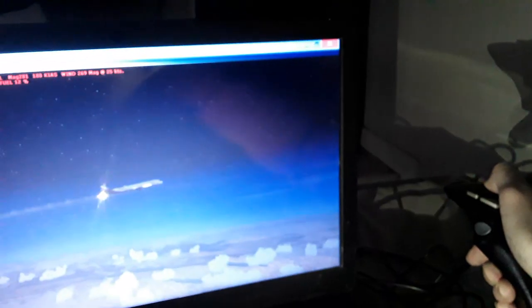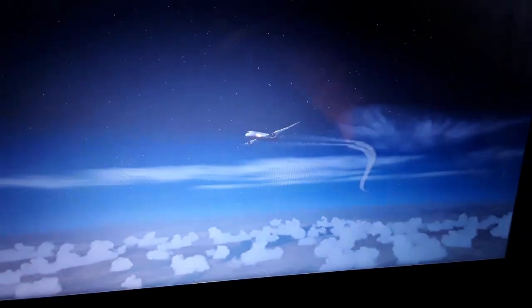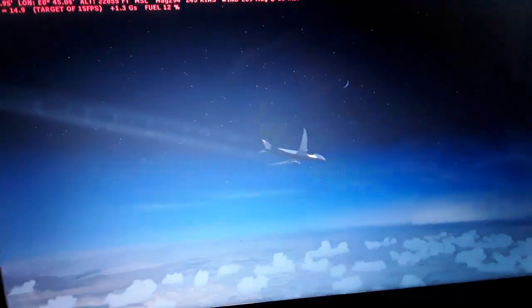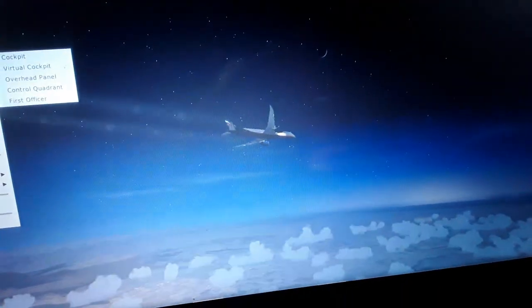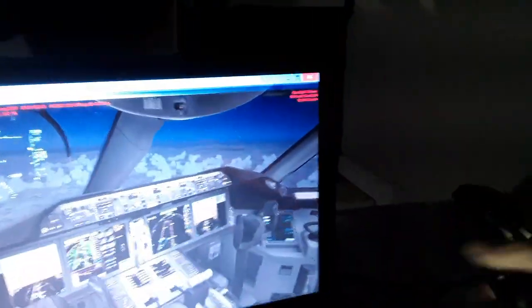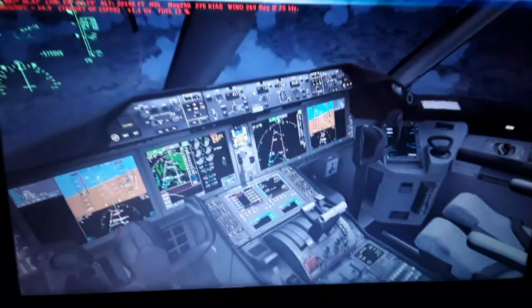So we can fly the aircraft, no problem with that. So we have Germany, my homeland, Germany, and France. So we start the descent now. So we use idle thrust over here for descent, and also speed brakes extend to increase the rate of descent.